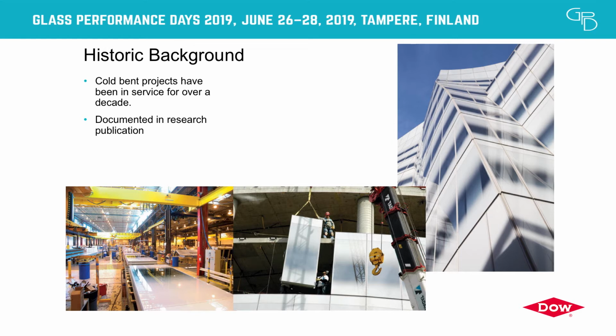There are a couple of benefits with cold bending. Building things that are flat is probably easier to tolerance. The challenge, though, is that you're putting a stress into them. And so the question is, how much stress can I put into the components of a cold bent curtain wall assembly? So this is going to be solely focused on what is happening to the sealant, and the research that we did to try to develop a more predictive model that hopefully can be used in FE in a more holistic approach.